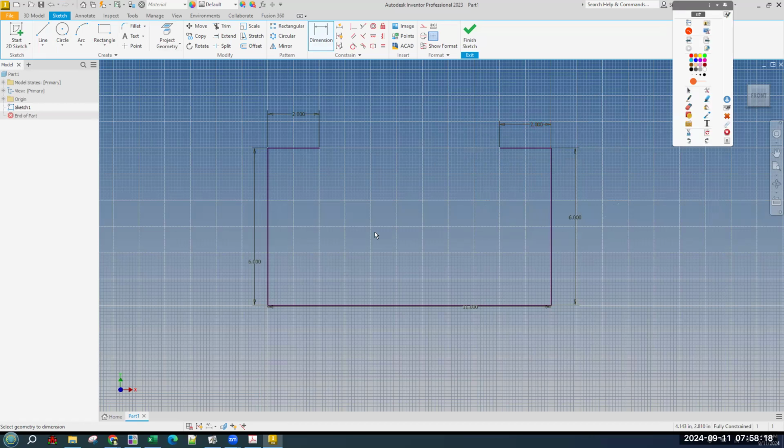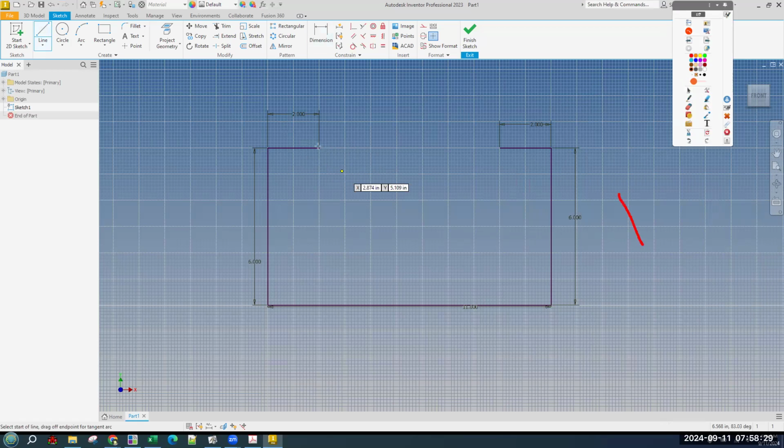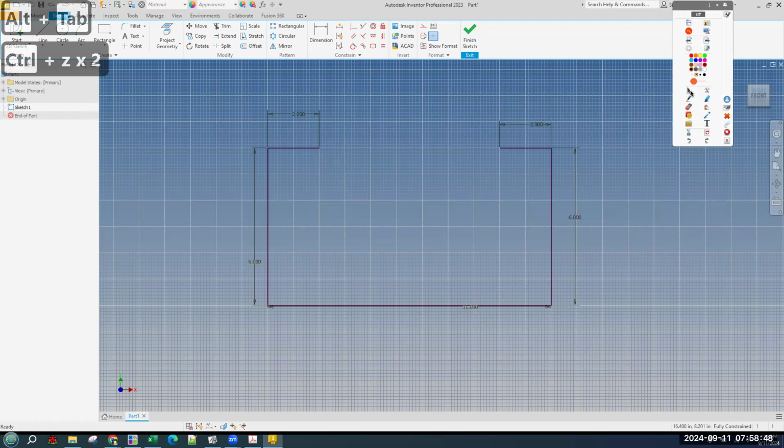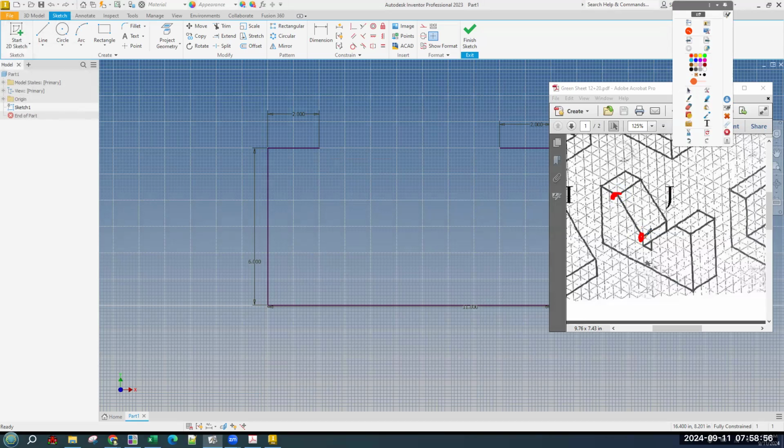All right, so here is one of the tricky things about sketching, and that is sloped lines. Okay, this line right here, we are not going to make a sloped line and then figure out, we're not going to do Pythagoras and figure out how long this would be. We could. It wouldn't be terribly difficult, but it's certainly not the easiest way. The thing about sloped lines is, as long as you know where they start and where they finish, you know the size and location of that line. It doesn't matter how long it is.